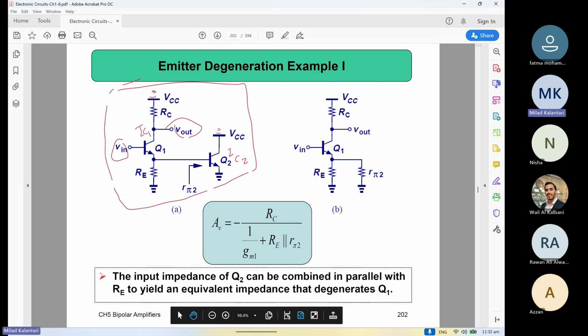Initially you see that this circuit is basically a common emitter with some degeneration emitter, right? And then there is something here. So from here, you need to find what impedance this thing is. This thing is just a simple transistor at the input. Even if you imagine the small signal model, what you are seeing is just the R pi.